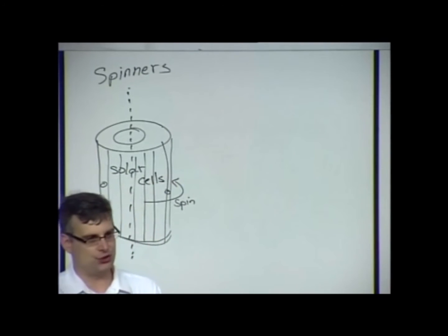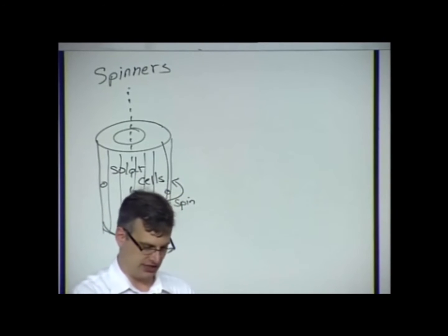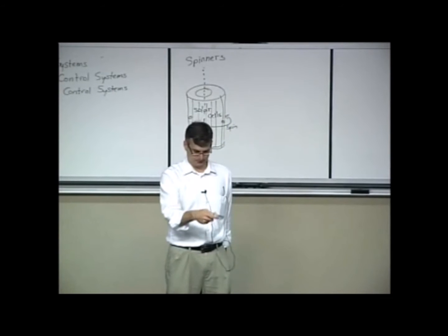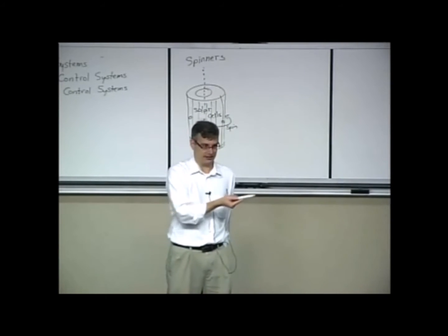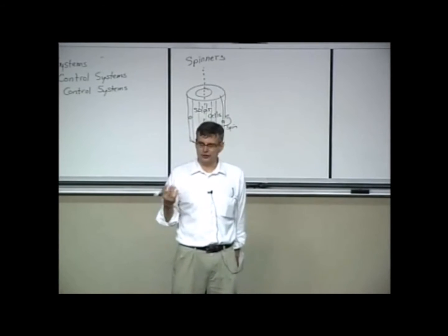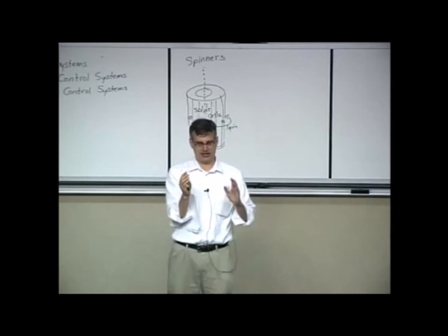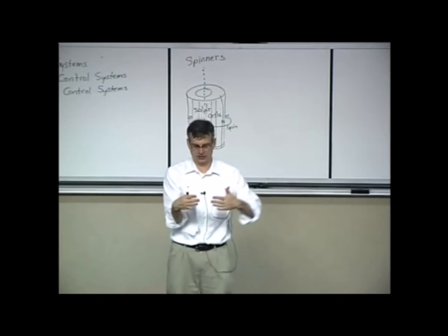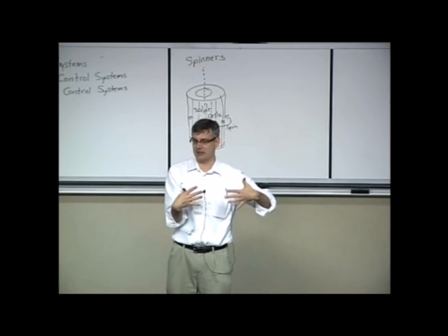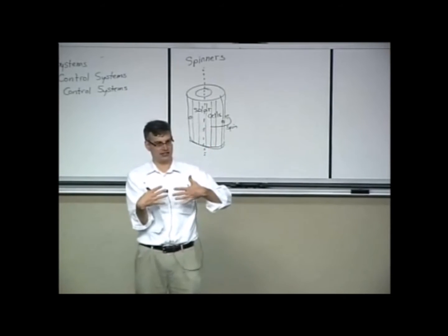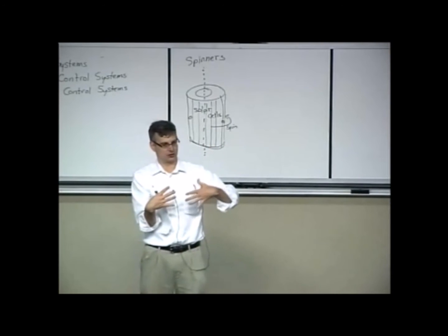Now, it's not the best use of solar cells because if you do a quick calculation, only one side of the drum is facing the sun, and a lot of the facets of that side are not optimally oriented. They're kind of off to the side, so they're not collecting maximal incidence. In fact, what you find is that if you were to compare the output of a drum-shaped arrangement of solar cells to an arrangement of solar cells that were flared out into a flat sheet, the same area, you would only be getting about a third of the power from the optimally pointed flat solar panel.